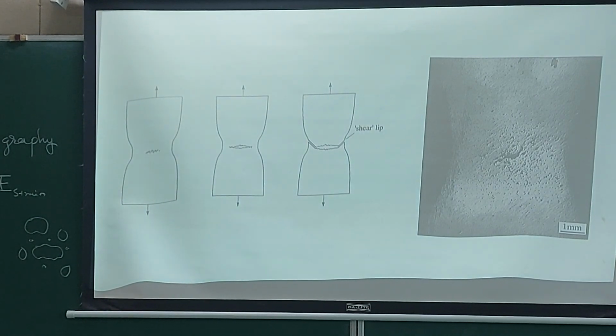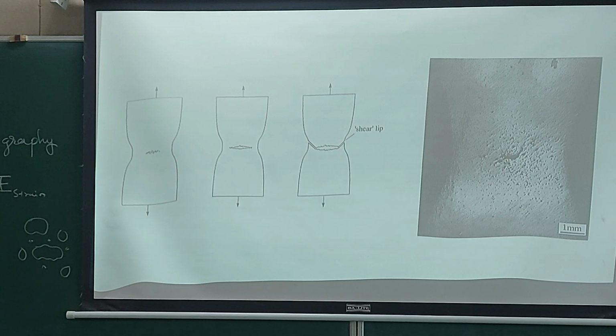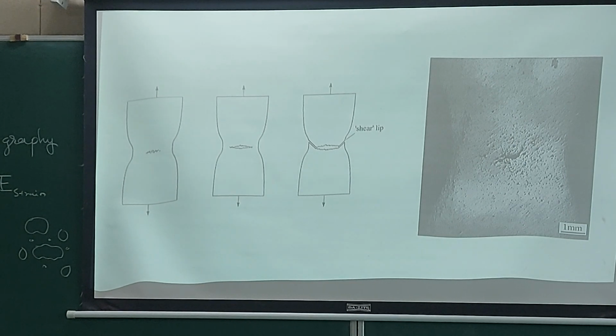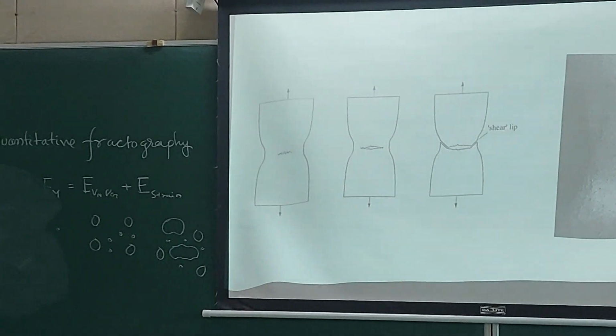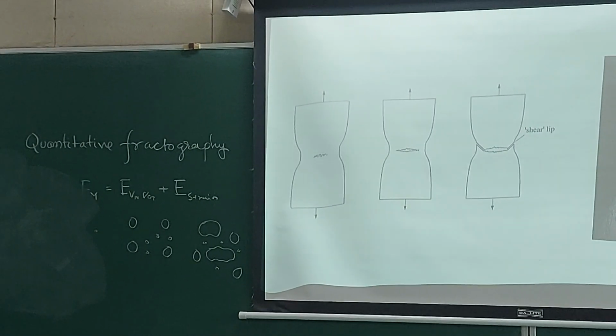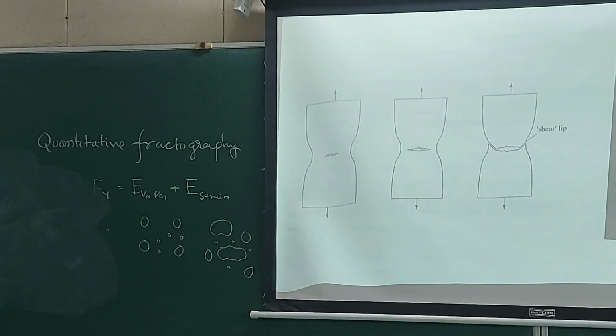So you have a probe, a stylus kind of thing, which moves through the surface, and then it notes down how many valleys and crests it has passed through, how much depth it has gone through, and it calculates an average of that, and that is a roughness value.